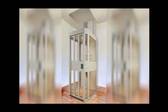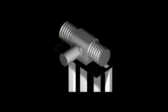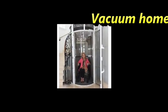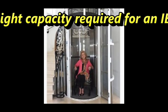First, the types of home elevators. There are the traditional cable-driven elevators and hydraulic elevators. The cable elevators wind and unwind a lift cable on a drum to raise and lower the elevator. The drum is turned by an electric motor. The hydraulic elevator usually requires a secondary equipment room that houses the hydraulic oil reservoir, a hydraulic pump, and an electric motor, all of which are more expensive than the cable elevators. There are also vacuum elevators that to date would not suffice in adequate size or load capacity for an IBMer sitting on his power chair.